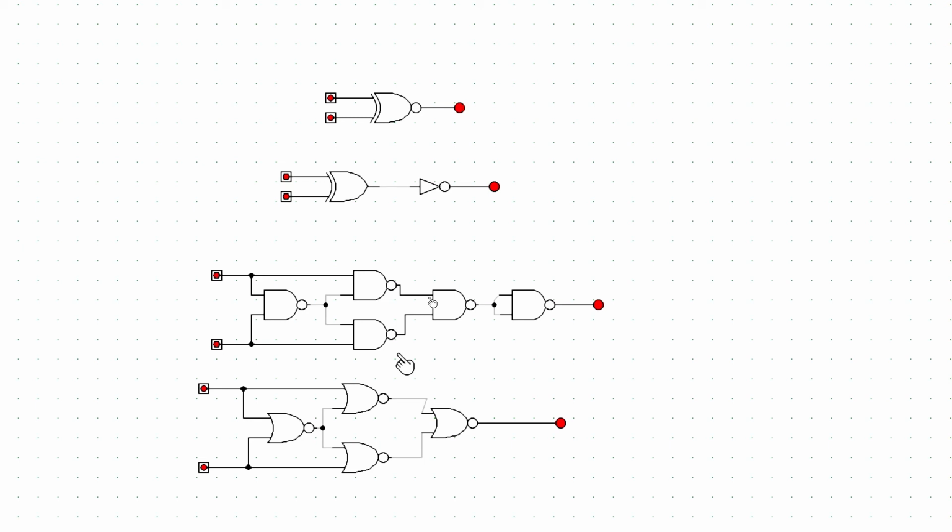The good news with that for practical electronics is that if you wanted to do some fairly simple digital electronics and you didn't know which gates you were going to use, you could just buy a whole load of chips that have NAND gates on them, or a whole load of chips with NOR gates on them, and you could produce any circuit that you wanted out of that as long as you'd got enough, because you can create the equivalency of the other gates.